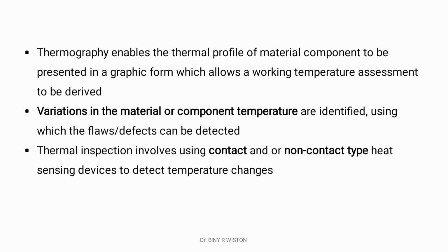Thermography enables the thermal profile of a material or component to be presented in a graphic form, which allows a working temperature assessment to be derived. From this, variations in the material or component temperature are identified, using which the flaws or defects can be detected.